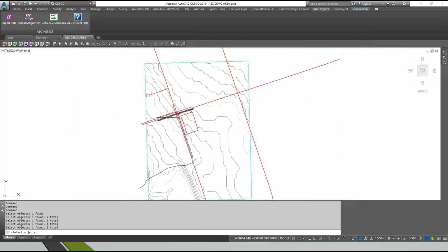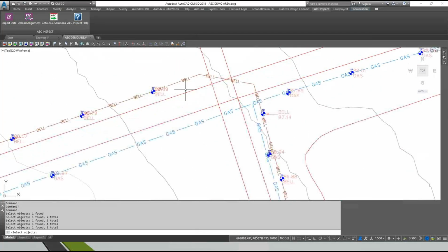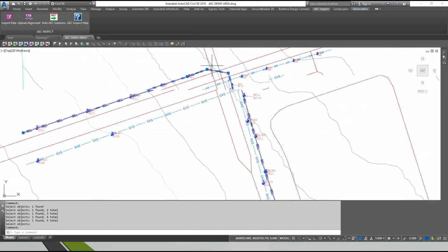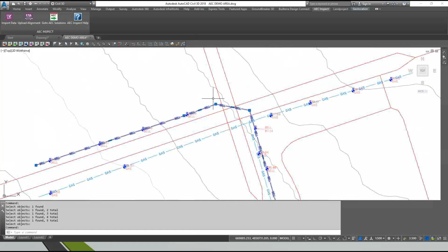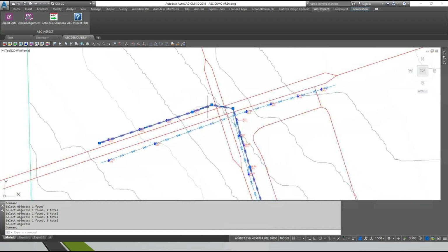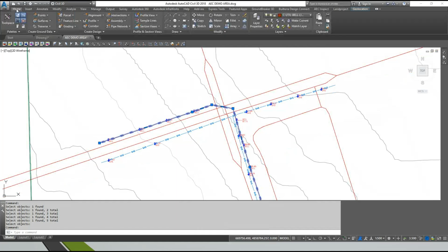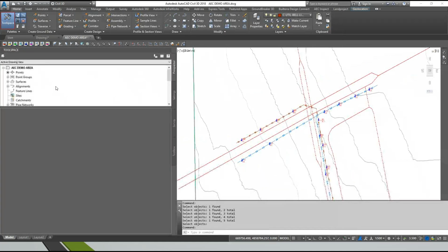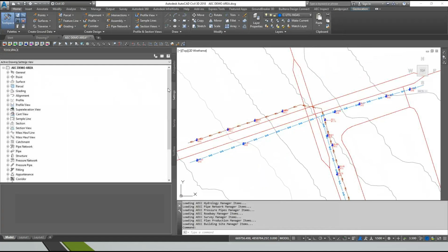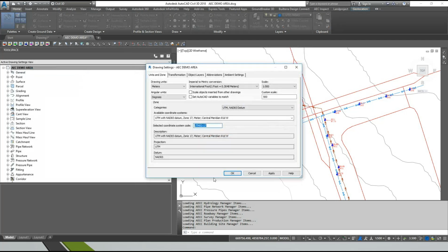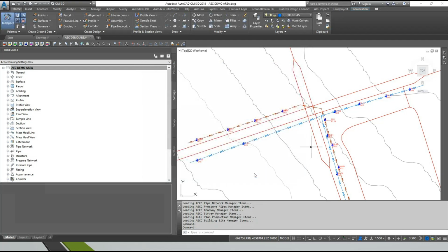Here's our data. This is our bell line that we're looking to see how close we are to. So what you may have to do is make a shapefile from that. Just like we had done before, you have to make sure that the UTM system is set as a part of that. UTM is what we support right now. If you need an MTM or something else, just add it. So UTM is what we're supporting.